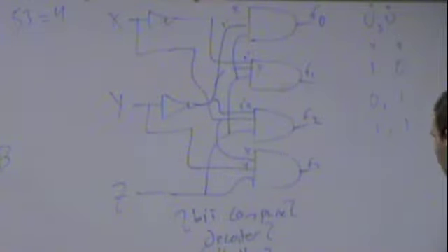Nobody has any questions about that because we already know. We eliminated 2 choices, and then we eliminated the compare because I did the truth table, or you could just look at it and go, that's not a compare, because it has way too many outputs to be a compare, because compares only have 1 output, a yes or a no, it doesn't say which one's greater kind of thing.